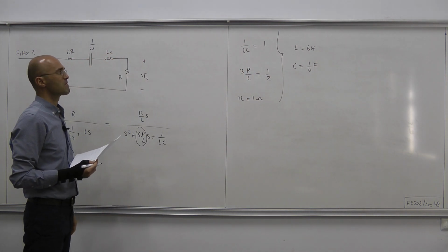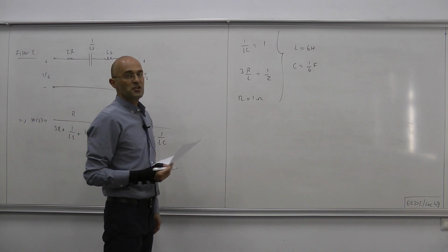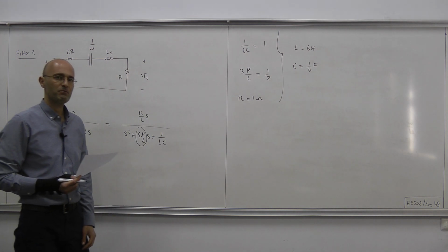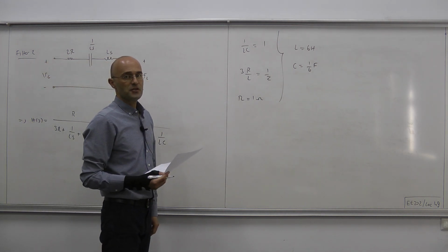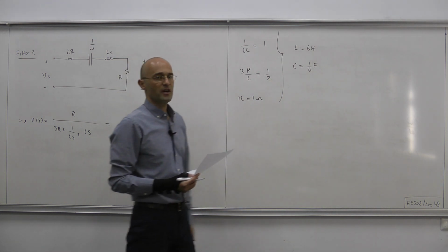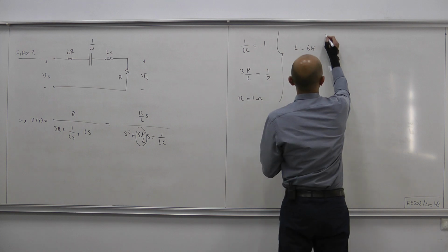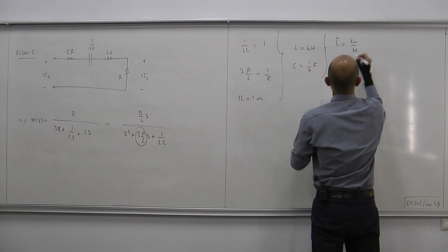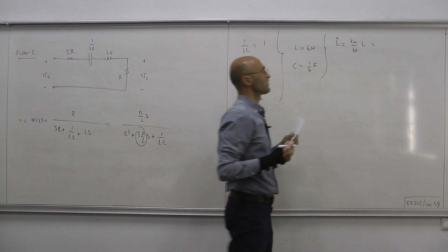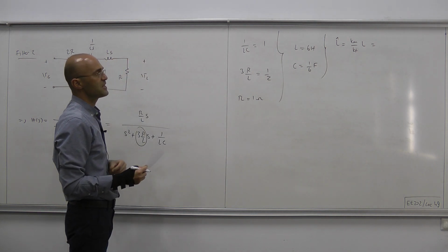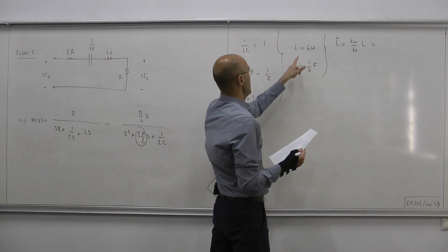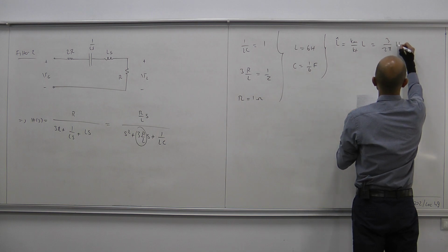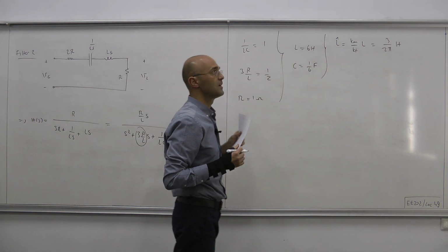This satisfies the design constraints of the initial design. But then we have to modify our design by scaling so that it fits the final design requirements. That's easy. L hat equals Km over Kf times L. Km was 2000, Kf was 8000 pi, and L is 6 henries. Therefore, this produces 3 over 2 pi henries. That's the inductance value for the second design.